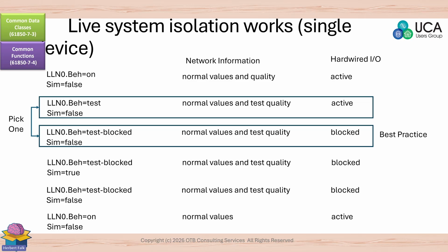There are some best practices, at least I consider them best practices, on how to wind and unwind testing and blocking, and this slide actually shows that. There is a mechanism in 61850 to say, I want to be allowed to accept simulated data, in other words, from the test set. So you put the device into test blocked.